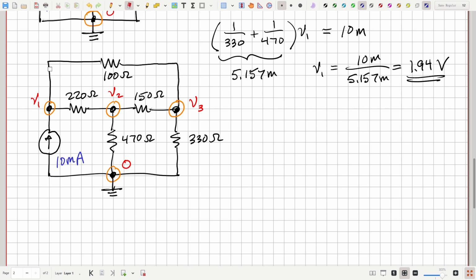And so we can have, let's call this current, say, I1A, and this current I1B, and the current going up here, I1C. And therefore, at the node with voltage V1, Kirchhoff's current law would be I1A plus I1B plus I1C is equal to 0. And now we put in terms of either the sources or Ohm's law what those currents are, and we get our equation.